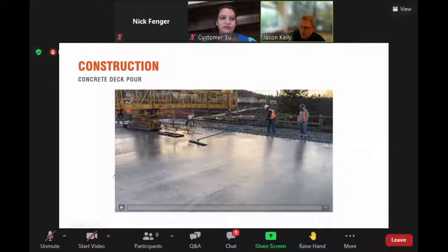And the last thing I wanted to show you was, or the last video was, of the bridge deck. So concrete placement for bridge decks is kind of unique in the construction world. We use what's called a Bidwell machine, and we use it because we want all the concrete to be dense, we want all the voids out of there, and we want it really nice and consolidated. But we also need a smooth surface because you're going to be driving your cars on it. It needs to be a smooth surface. So we use what's called a Bidwell machine, and it's kind of unique to bridges.